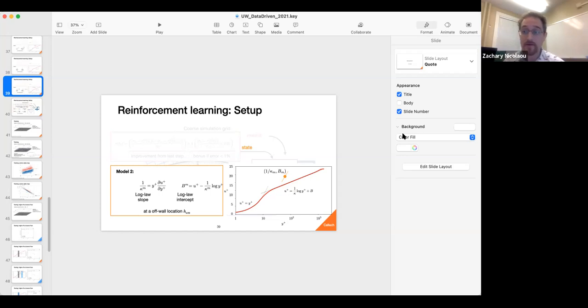Great. Okay. So next from Diraj says, as a follow-up on the previous question, is tau sub omega the ground truth from the LES simulations? Are the agent's actions being used while training? And do you discard simulations where the agent is way off? Yeah, so basically the tau wall model is the wall shear stress obtained from the model. So the model at any point gives a wall shear stress, and that's what the tau wall model is doing.